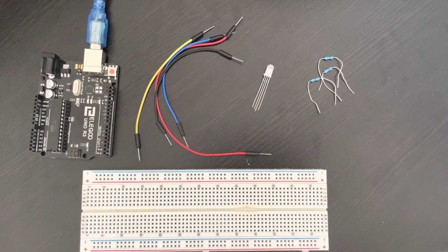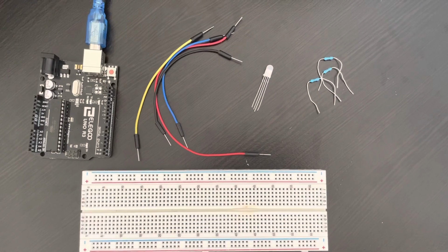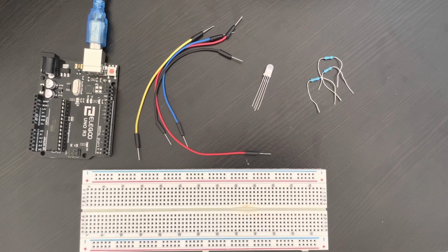0 makes no pulse, while 255 means that it makes a full-powered pulse that lasts all the way until the next pulse is due. If the value is between 0 and 255, then a pulse will be produced. For example, if the pulse is only high for 5% of the time, then the device only receives 5% of full power.